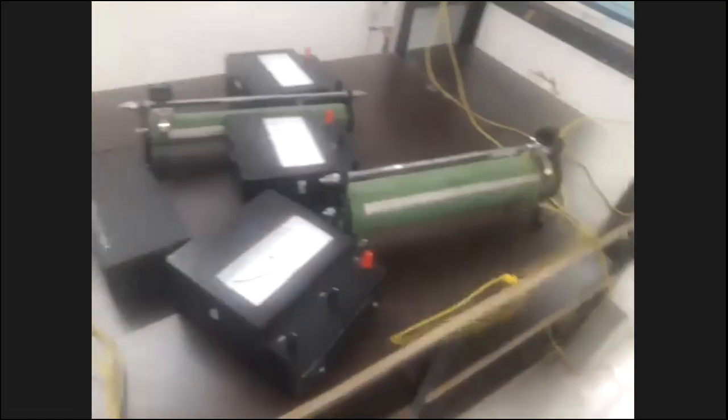Now F1 and A2 get short circuited. The next connection is the armature terminal of the 3-point starter, that is the A terminal. The A terminal of the 3-point starter is connected to the A1 terminal of the DC motor. The motor and generator form a coupled set.